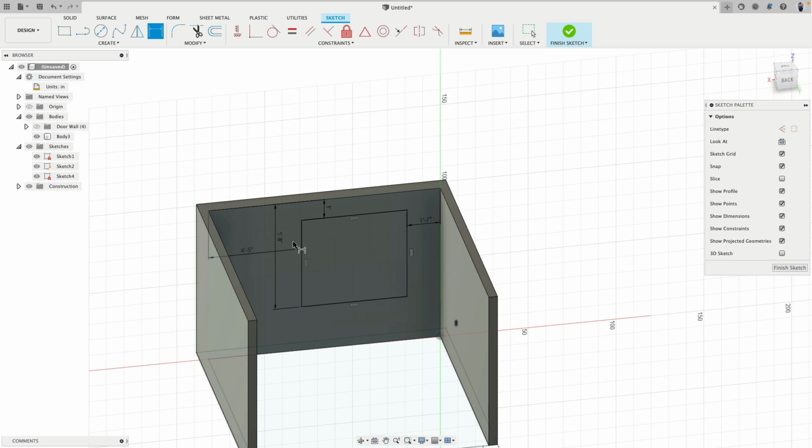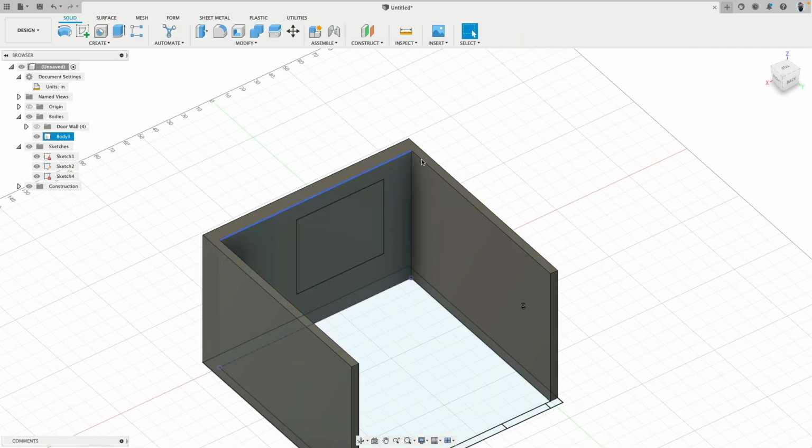And then we can do the following, and because this looks kind of crazy, we delete this dimension and then say, hey, just write me that. So 2 feet, 4 inches. So what I have now is actually the outer dimension of the window trim, and not necessarily just the window opening itself. Click finish. So this is all good.